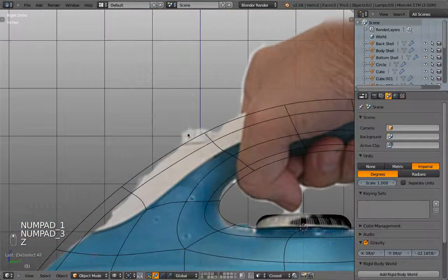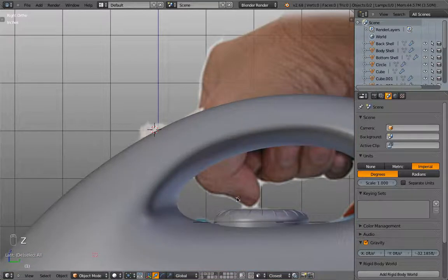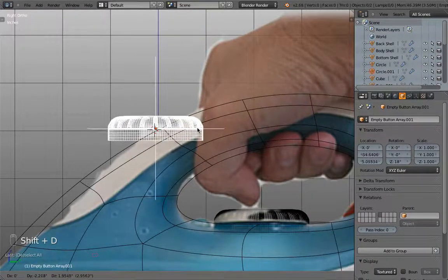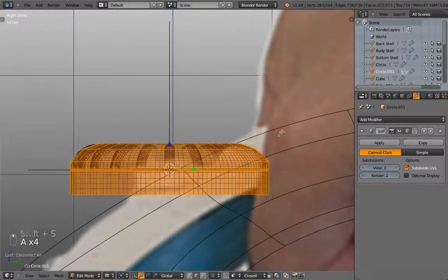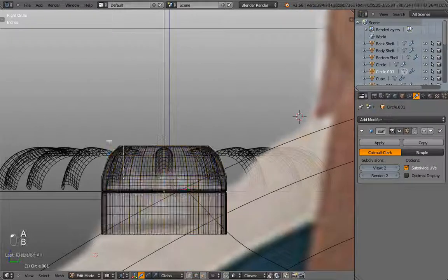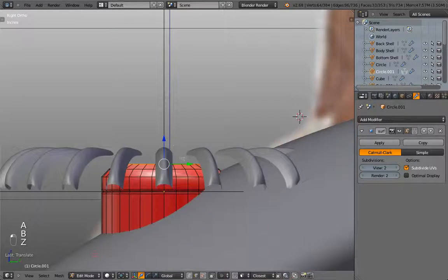Now let's take a look at the top part. That's a different type of button because, instead of geometry coming out, we have geometry coming in. So I'm actually selecting all this, press Shift D and duplicate it. Cursor to selection, and then here maybe S and Z. Scale everything down. So you see I just recycled some of that geometry.